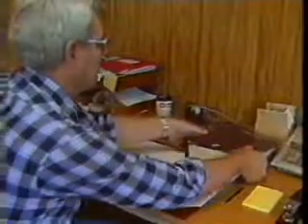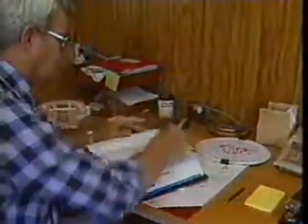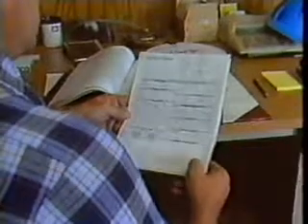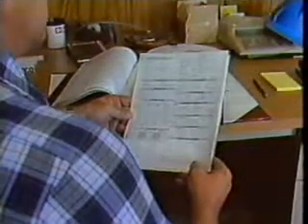Be familiar with the current edition of ANSI, API, and GPA standards for NGLs. Be sure to have a copy of the contract brief for the facility. Take some time to review the history of the operation by comparing production reports with actual sales volumes for this location. Also review the reports for plate size, chart readings, and volume calculations.